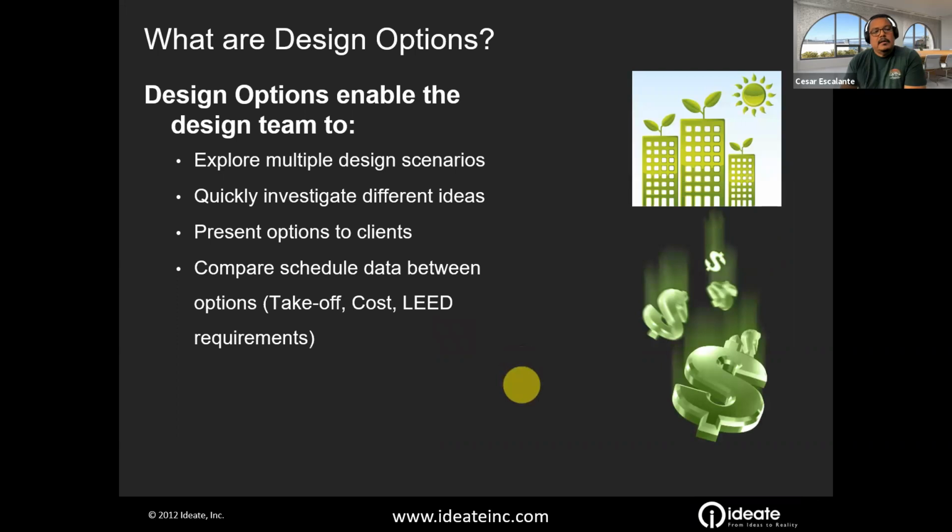You can compare design options using view-specific, design option-specific schedules. Design options become an instance parameter of the objects, which allows you to create and compare data between them. Scheduled data could be compared. You can actually make quantifications, differences in cost, with requirements, etc.